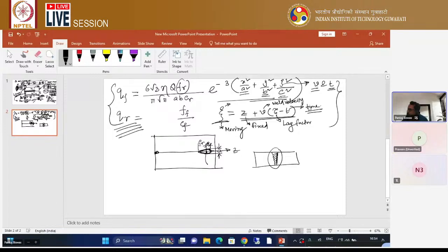And to get the B value, what is the B parameter? What you need to do? You need to take a cross section. Let this be your x cross section. You need to cut it. After cutting, you do the etching operation; generally for steel material we use nital solution.